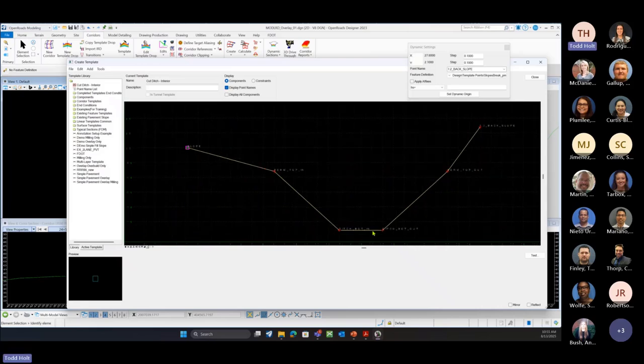That's going to draw, but it's not going to start drawing until the existing ground hits this point and goes above, because this is the end condition that's drawing. So in the criteria that we're building into this, it's not going to draw this ditch until that existing ground covers this point. And then from here, it's going to go and find the end condition. So this last segment is really controlling this ditch.